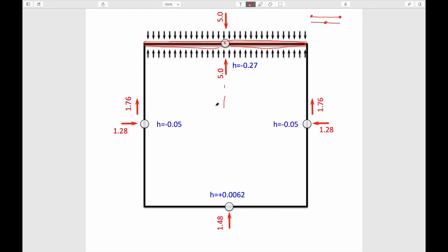So certainly as you go further out, you'd expect this cone of depression, which is what you can think of in terms of the pressures, that these would be higher than these values, which would be higher than this value. These are symmetric to each other, as you'd expect, just because of the symmetry of the problem. And this value here is smaller than this. You can imagine because it's just further out. So those are the solutions for the kernel functions that we'll work with.